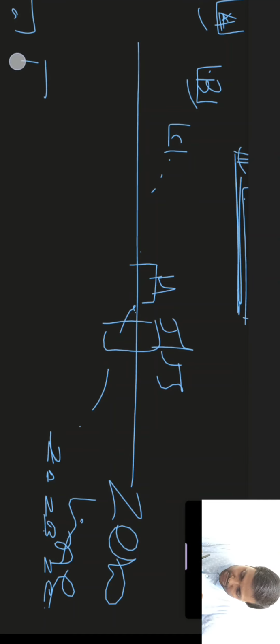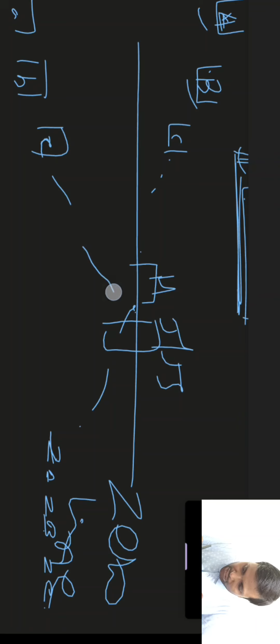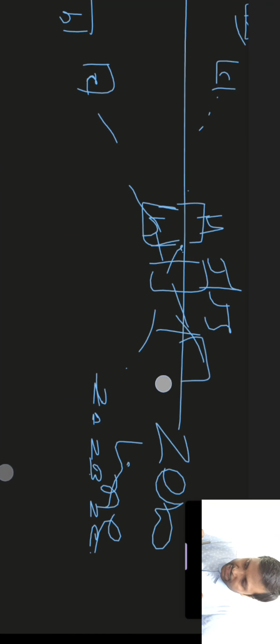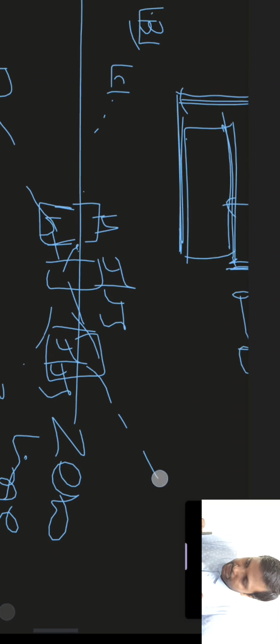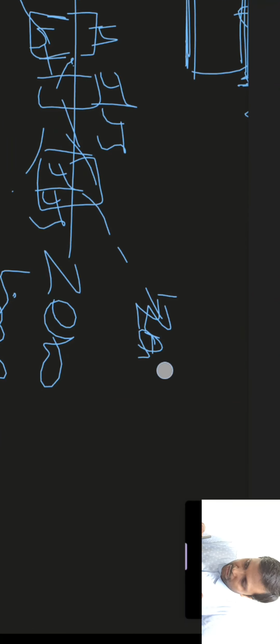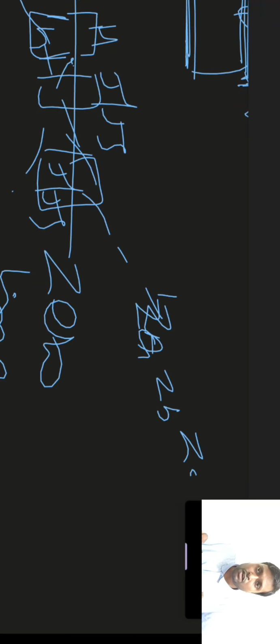Another fundamental deviation for the shaft is b. All these will be represented by a small letter, and it will move to a small h. This is the fundamental deviation for the shaft, small h. Next there will be j and js, and then it will move to small z, small za, small zb, small zc. So all these are standardized fundamental deviations.